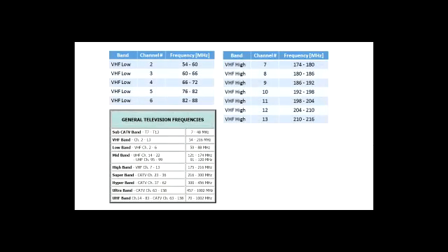All right. Now, I'm not going to go too much into that. However, there are some frequency bands, and these are the television channels here. Television channels 2 to 13, like that. So let's say if you're talking about cable television, channel 2 has a bandwidth between 54 and 60 megahertz. So you can see that it has 6 megahertz. It needs about 6 megahertz of space to carry the different signals involved in transmitting channel 2.